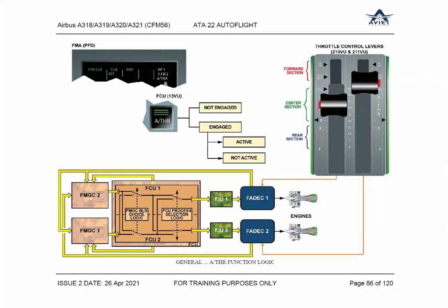And I have asked the pilots: even if TOGA thrust is applied, they will not move the lever to TOGA. They will leave the lever wherever it is. They will simply use this button, nothing more than that, just to disconnect, and that's it. Keep silent, observe the aircraft. Clear, sir? Yeah. Thank you. Welcome, sir.